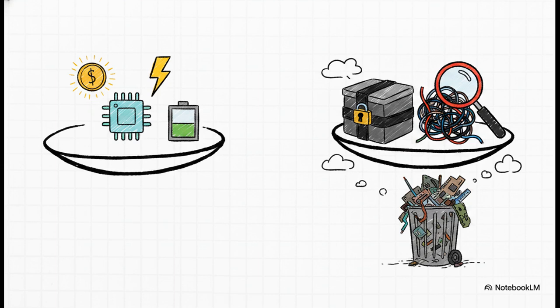Now, the design of these systems brings immense benefits. They are incredibly small, they're relatively low cost to mass produce, they sip very little power, and they offer extremely fast reaction times. But, putting my teacher hat back on for a second, I have to point out the significant drawbacks. Because they are so highly integrated, they are notoriously difficult to upgrade. If a non-programmable embedded system needs a simple software update, you often just have to throw the whole thing out and replace it. And troubleshooting them, that is a highly specialist task.